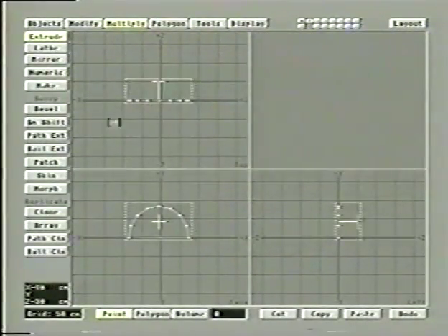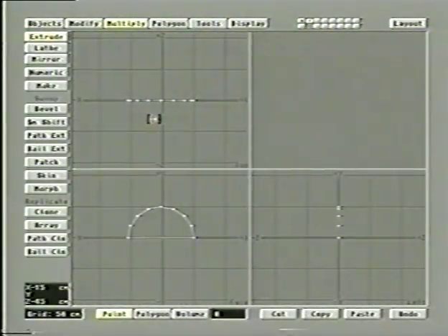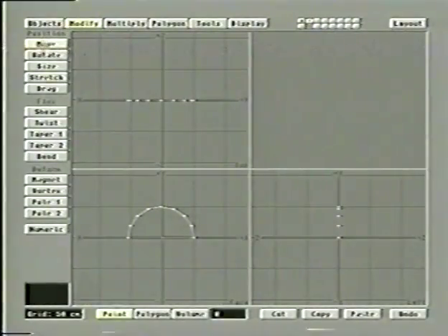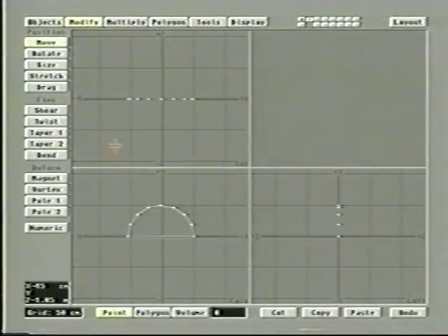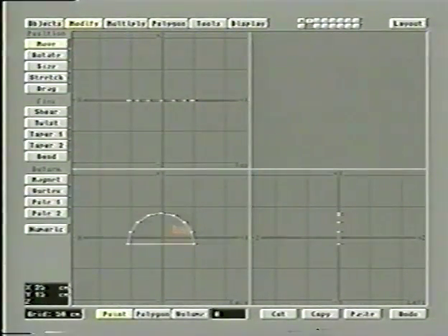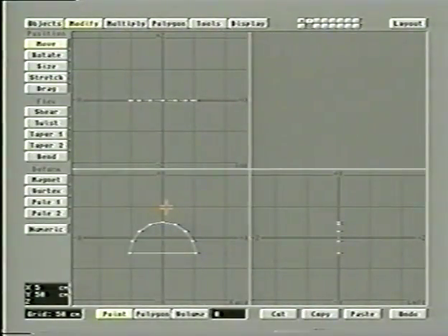Now, of course, you could draw it anyway, but as you can see, sketch mode is a quick, easy way to draw shapes like this. So here's what we're going to do. Let's undo what we did there on this shape. So we'll bring it back to 2 dimensions. What we want to do here, let's actually move this down a little bit so it's more centered. Quick way is the F1 key, or I could move it manually, but F1's quicker. So this is centered up.